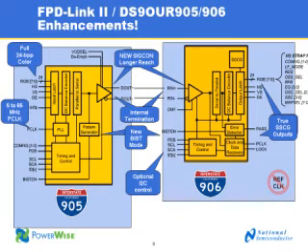Now moving on to the interconnect, a couple things we've done here. Remember, we're running higher speeds and we want to still support the long 10-meter cable length or longer. So we've added some signal conditioning. This includes de-emphasis at the serializer output and also equalization at the receiver input. We've also integrated the terminations, which allows for really simple board design, not a lot of components. We've enhanced the built-in self-test mode. This allows the serializer to generate a pattern, and this is tested at the deserializer for a self-enclosed test system and validation of the link between the serializer and deserializer.